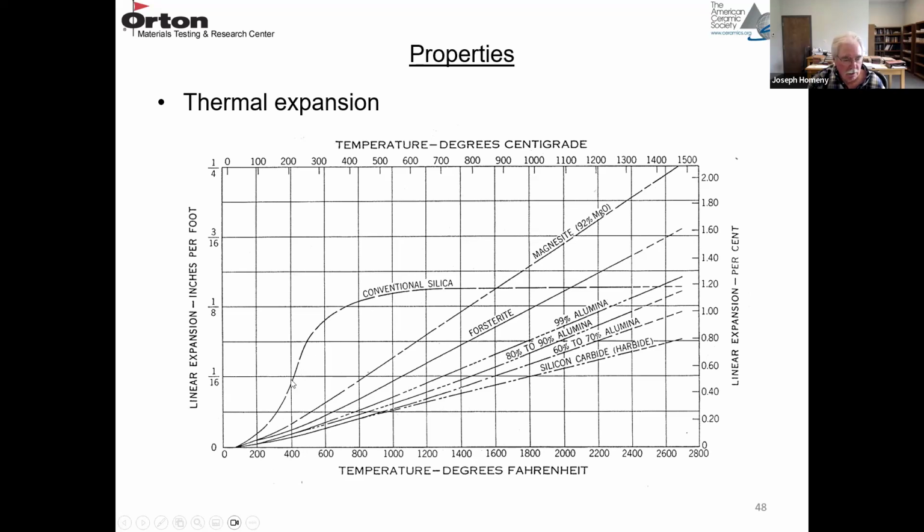You can see in this low temperature region the displacive transformations, the cristobalite and tridymite transformation. So there's a rapid increase. And then because of the open structure, you have very little change in size. So the thermal expansion tends to be rather flat. So here, if you put this refractory in a furnace, you have to heat up slow in this region, and you can go faster in this region.